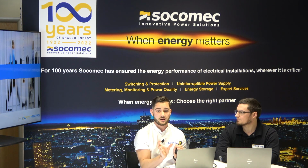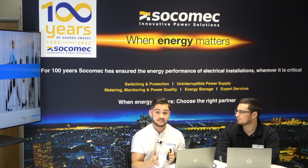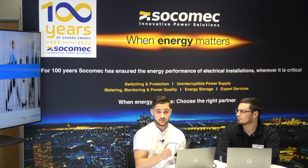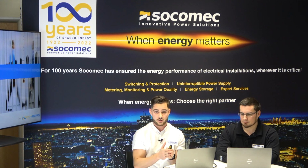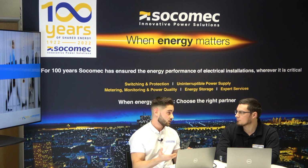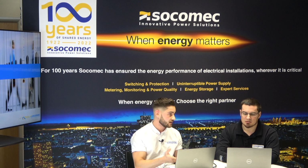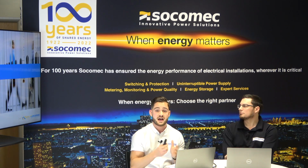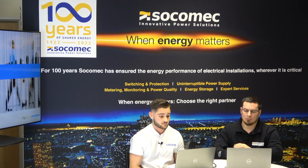Just something we need to keep in mind, and we've covered that in the previous STS live stream. The neutral will be overlapped to keep the earth and neutral reference, but the switching time will be exactly the same. So typically 3 to 5 milliseconds. Unsynchronized transfer, we would say around 10 milliseconds, 12, yeah. And still below the 20 milliseconds specified in the ITIC curve. Yeah, good answer.